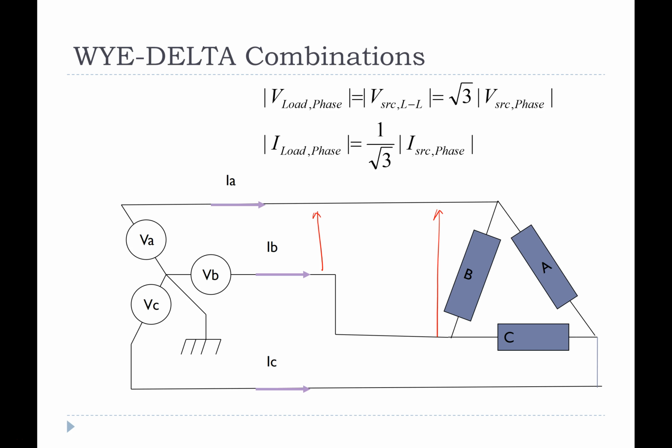So in this case what you would have is that the phase voltage on the load is equal to √3 multiplied by the phase voltage on the source. So just by connecting this in a different way, you could get an increased voltage on the load components. It is not necessarily that you have to get something higher, lower or the same as you would expect from single phase systems.